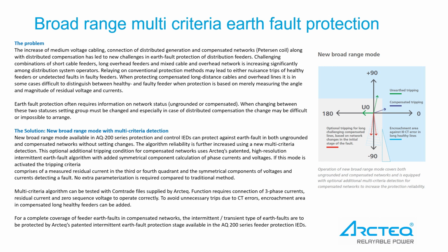The multi-criteria algorithm can be tested with Comtrade files supplied by Arcteq. The function requires connection of three phase currents, residual current, and zero sequence voltage to operate correctly. To avoid unnecessary trips due to CT errors, an encroachment area in compensated long healthy feeders can be added.